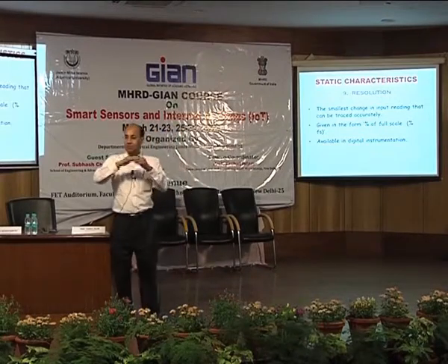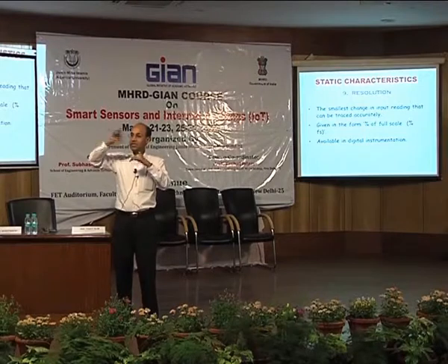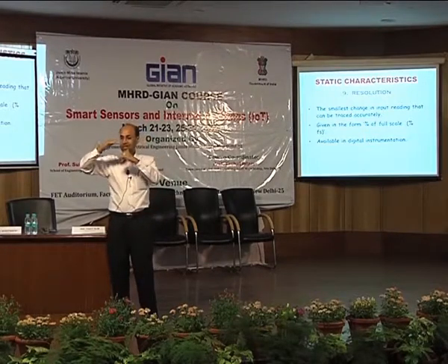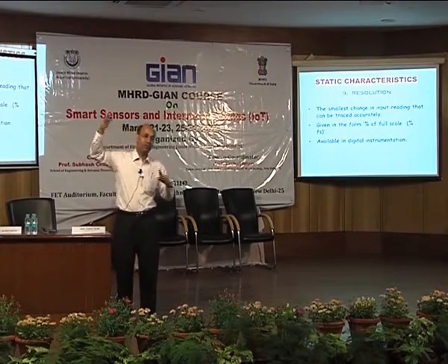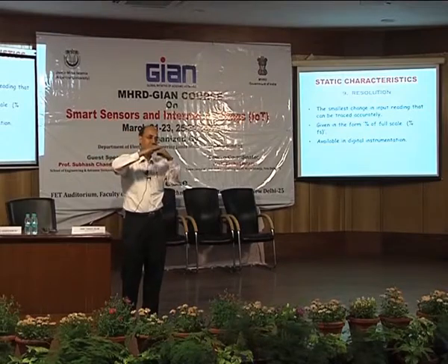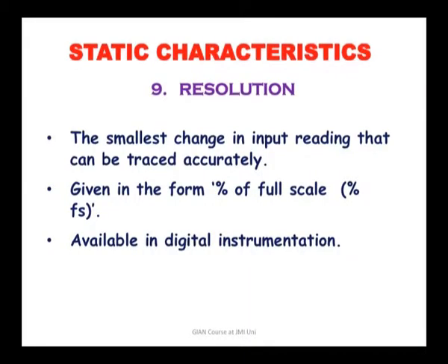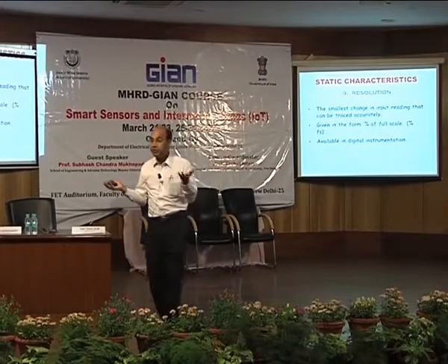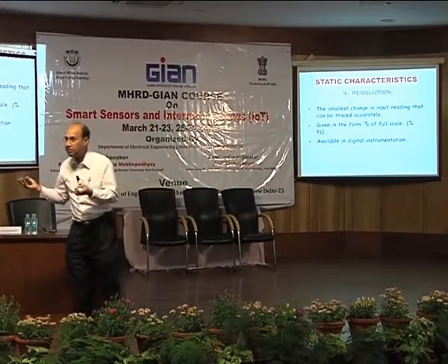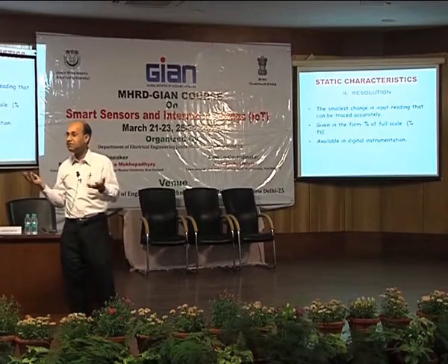From one step to the other step, how much is in between? It is like a dead band, okay? So how much is that dead band? If you go for a larger number of bits, you can reduce the dead band. So that's the resolution, which is very, very important. We do not tell resolution in terms of absolute value. We always say 8-bit, 10-bit, 12-bit, 16-bit, like that.